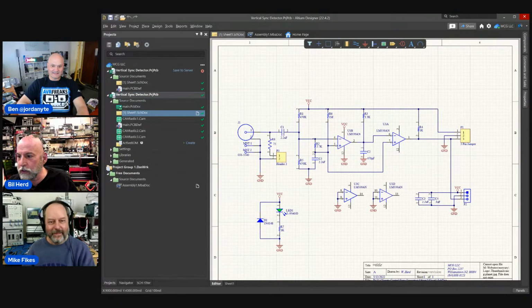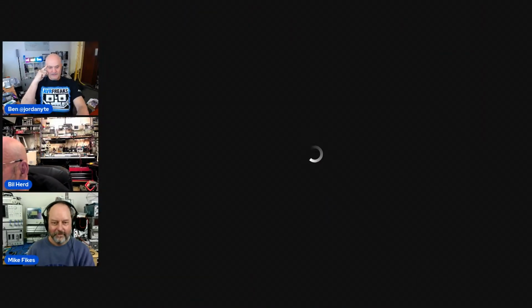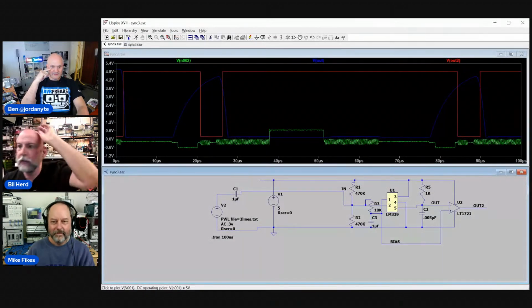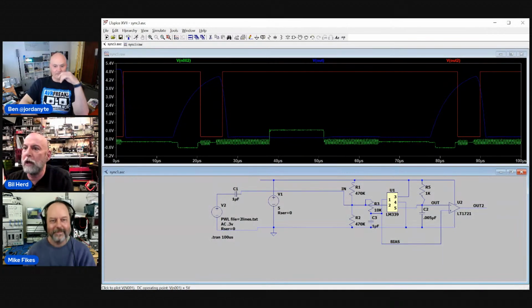And if I show the circuit again, now that I've explained that, your simulation, I could see that in the waveforms. So it generates a fixed width negative pulse on detection. And so there it did it. And I've actually plotted in blue, it's hard to see, but in blue, that's the actual RC value too.